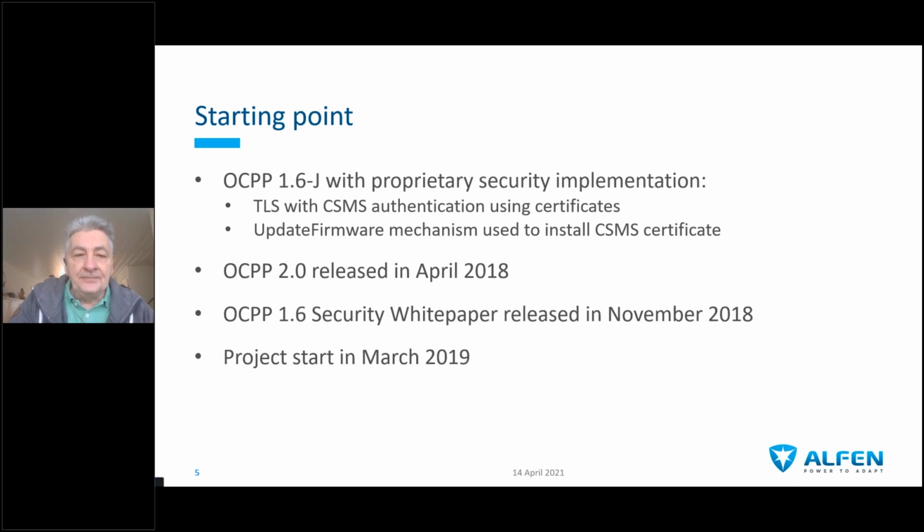What we did from a starting point, we had OCPP 1.6 JSON with a proprietary security implementation. We were using TLS with back office authentication and certificates. And to install such a certificate in the charging station, we misused, let's put it that way, the update firmware mechanism.